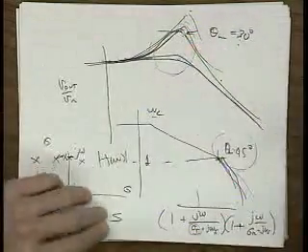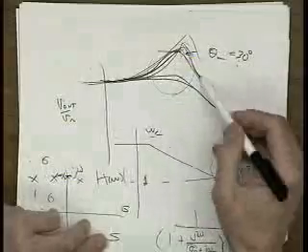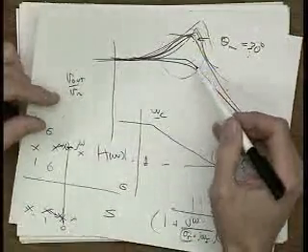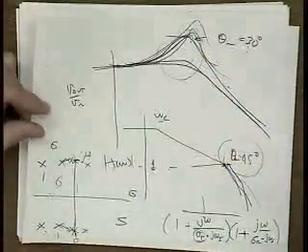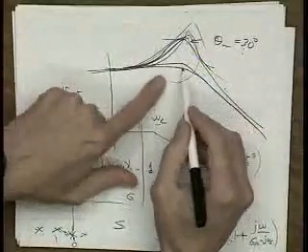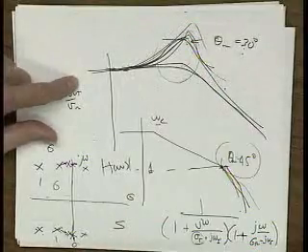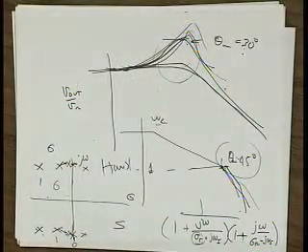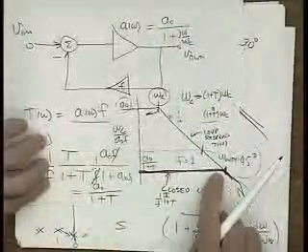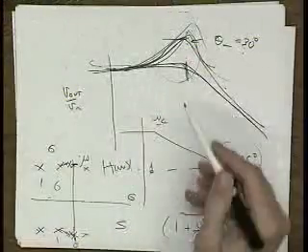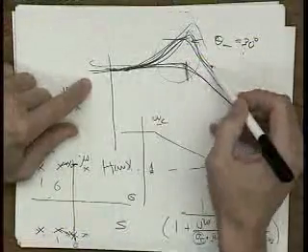Now, let's finish up our little story from earlier today. So this peaking here, what does that do? This is frequency response, the frequency domain response. What does that do in the time domain, which is what we're talking about in our small signal settling response, right? Remember we talked about this being the closed loop amplifier response. This is what I was talking about a little bit earlier, about having this closed loop amplifier have a higher and higher response. Well, that's this number right here. This is that plot right here. As you have less phase margin, you get this peaking here.